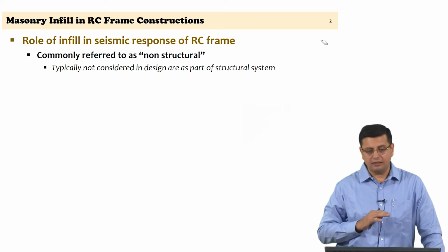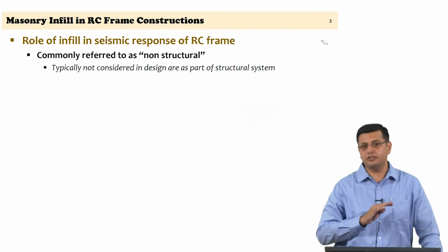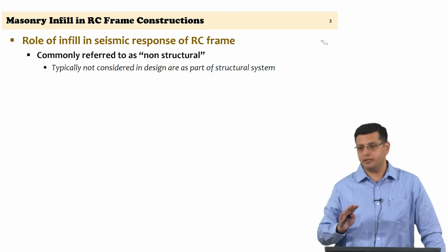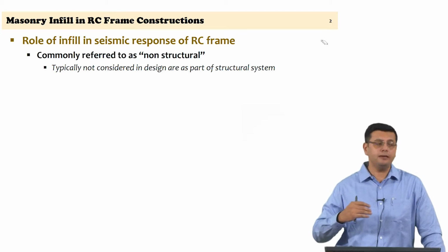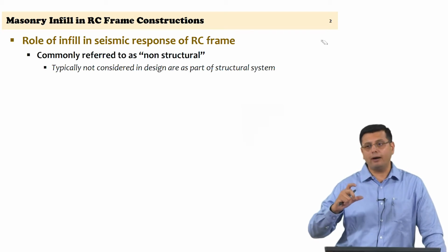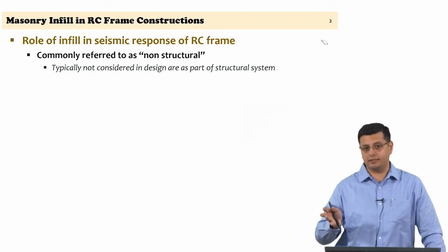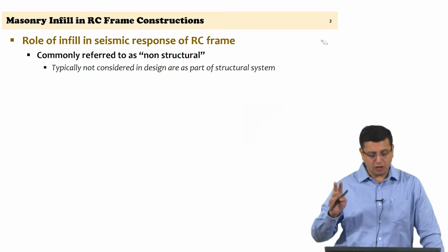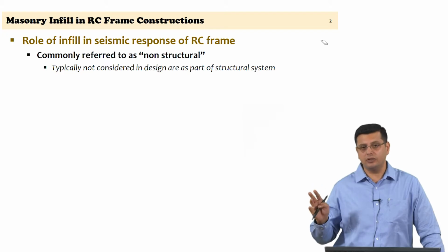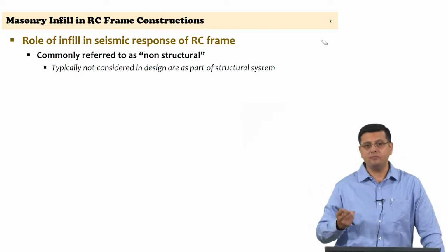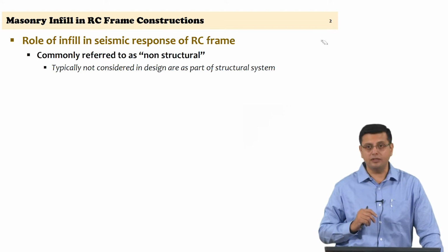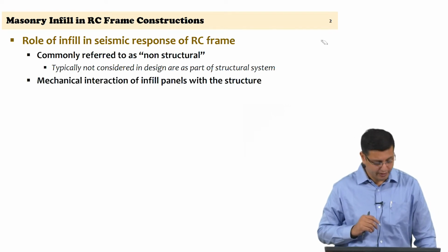So, in standard design this is not considered to be a part of the structural system, which is fair because we do not expect the infill panel to be a part of the lateral load resisting system. So, from that perspective, not considering this as a structural element within the structural design is meaningful. However, there are issues that come because of the possible interaction, and that is what we are really interested in.